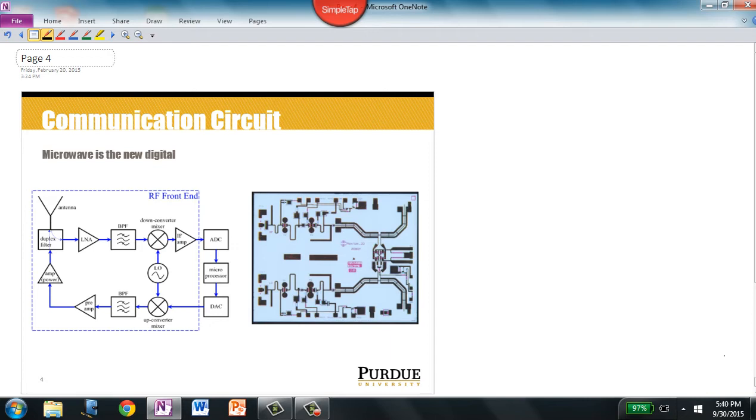And really, no matter the technology implemented, communication systems will typically use a transceiver architecture that is similar to what I'm showing here, and hopefully you've already studied this in your communications courses. So this is a radio frequency front end. We've got an antenna, and the antenna has a filter on it. It's called a duplex filter because the antenna is being used for both transmission and reception. In the case of reception, the received electromagnetic wave gets converted to a voltage and current, and therefore power goes through a low noise amplifier.